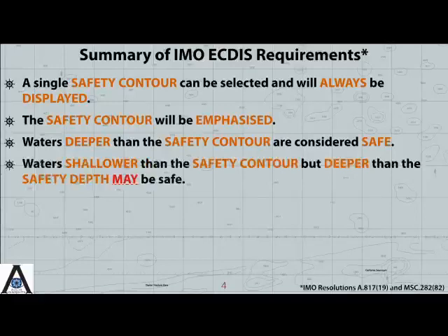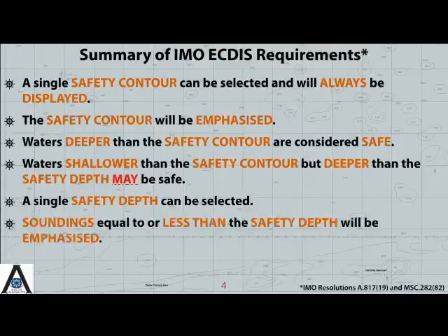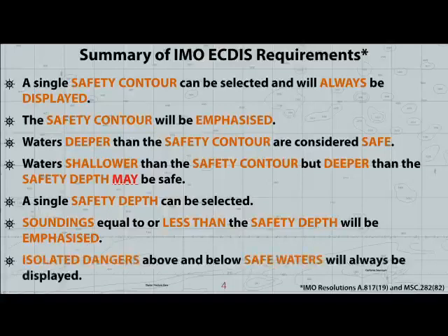Waters shallower than the safety contour but deeper than the safety depth may be safe. A single safety depth can be selected. Soundings equal to or less than the safety depth will be emphasized or shown in black type. Isolated dangers above and below safe waters will always be displayed.